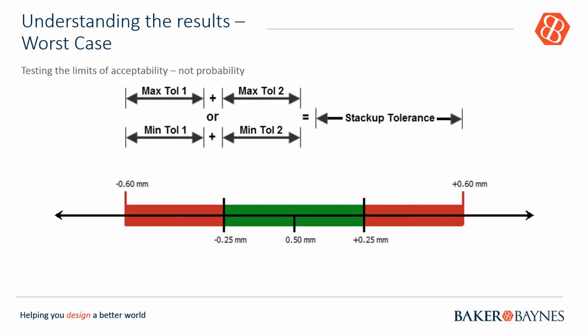Now let's talk briefly about the results and what we can expect from Inventor Tolerance Analysis. The simple result is the worst case scenario. This is the result that is easiest to calculate by hand for a small quantity of parts. In this case, we simply add up all of the tolerances from the components and compare them to the tolerances of the gap. We might assume that we need to tighten up tolerances, which can lead to more expensive inspection techniques and more parts being scrapped for non-conformance.